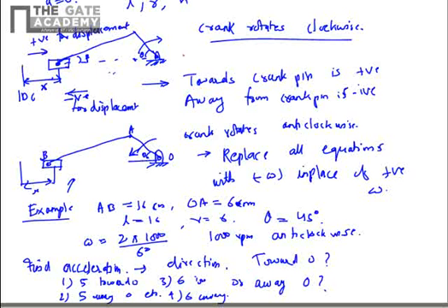In that case, you remember our original derivation was for the clockwise crank rotation. You put the values L, R, theta in the equation for the acceleration that you already know. Acceleration is omega square R into cos theta plus cos 2 theta by n. And when you are putting theta like this, here you get the absolute value. And in our original case, the theta was in direction of the crank movement, so theta was taken as positive. In this case, theta will be taken as negative. So you will substitute minus 45 degree in this expression and get the answer.